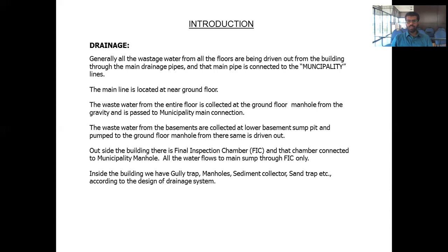Here also the wastewater has to be directly connected to the manhole. The water reaches the manhole by gravity only, so you have to give an appropriate slope. After the manhole, it passes into the main municipality connection. The wastewater from the basement is collected at the lower basement sump pit and pumped to the ground manhole. From this stage it is driven out.